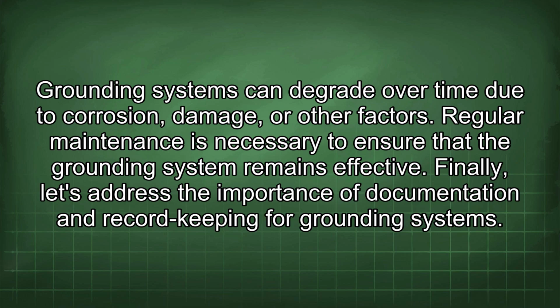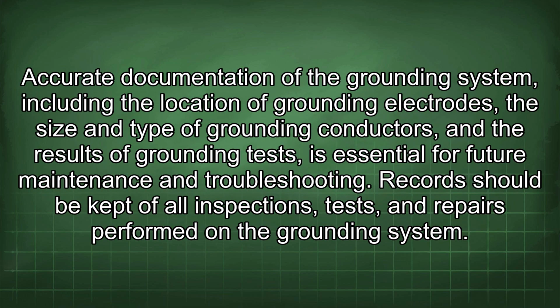Finally, let's address the importance of documentation and record keeping for grounding systems. Accurate documentation of the grounding system, including the location of grounding electrodes, the size and type of grounding conductors, and the results of grounding tests, is essential for future maintenance and troubleshooting.